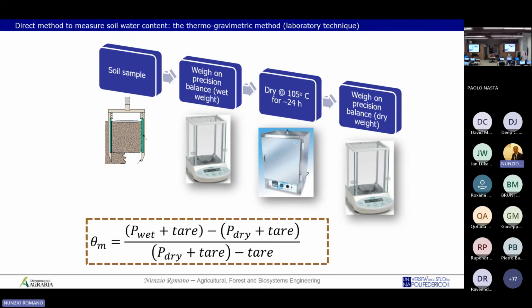The other point is the time that the soil core remains in the oven. You can see here, just as a schematic, it is 24 hours. It's a sort of lower threshold, but it depends on the type of soil, basically on soil texture. So you can have 24 hours for sandy soil, but if you have a clay soil, where the binding of water to the particles is higher, you may need even more than 36 hours.